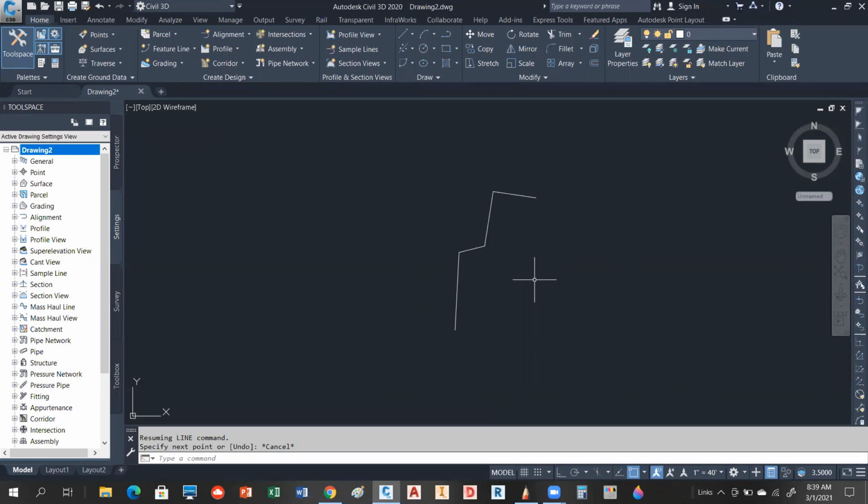And so the next line that we're going to establish is that east line of the boundary, and that has an azimuth given of 185.56.44. So the downside to that, it really doesn't tell you that's an azimuth, but it certainly couldn't be a bearing because it doesn't have a quadrant, and, well, it exceeds 90 degrees.